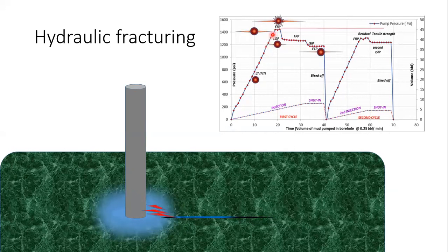Still, the pressure will rise until it reaches the fracture breakdown point. This is the point where it will suddenly create a bigger fracture, a small kind of fracture inside the reservoir. It is an empty space that was generated by the fracturing fluid. So it started to enter into the channels and reached the leak off point. After the leak off point, the pressure still rose to a level where the formation couldn't handle it. Because of that, a bigger fracture will be generated from the channel. That is the point we name the fracture breakdown point.